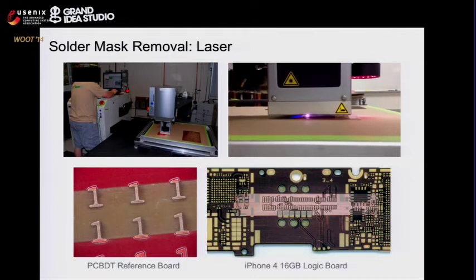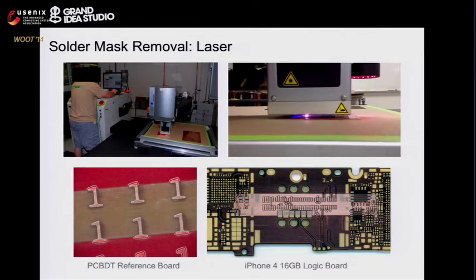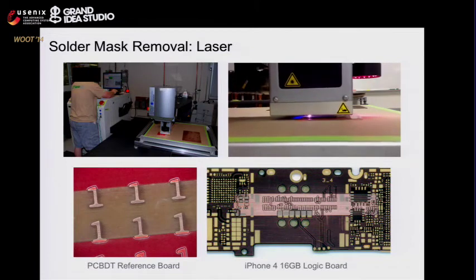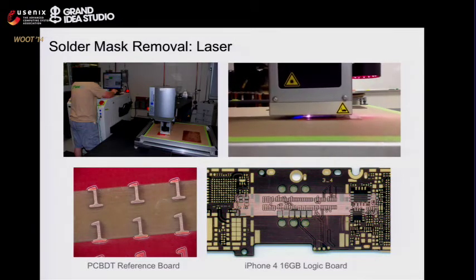Using lasers, another really awesome thing. I thought it would be great for getting access to the inner layers, but it turns out it's not so great because laser energy reacts differently to copper versus the substrate, which is usually a fiberglass epoxy. If you just had a laser going across, you would burn through the substrate faster than the copper. That's what we realized. But for removing solder mask, it actually is great. Here's a picture of some time I rented on a machine, with just some single passes right across the board. These are found in all sorts of hacker spaces these days, so it's a pretty easy way to do it. But still, using sandpaper to me is still the favorite.